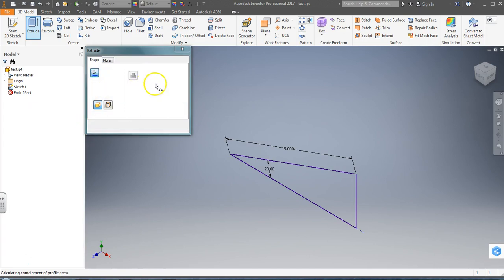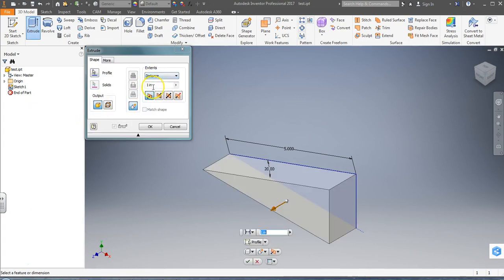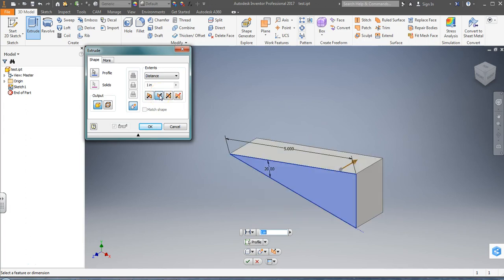This extrude, I can set my distance. Here's my distance. I have some choices. These choices here also work this way. So notice it's growing out towards the screen. If I change this, it goes away. I like my sketch to be on the top. This is also Z0. It makes things easier when I go to put a toolpath to it and I have to locate 0. I set my depth. I'm going to go with the default 1 inch.